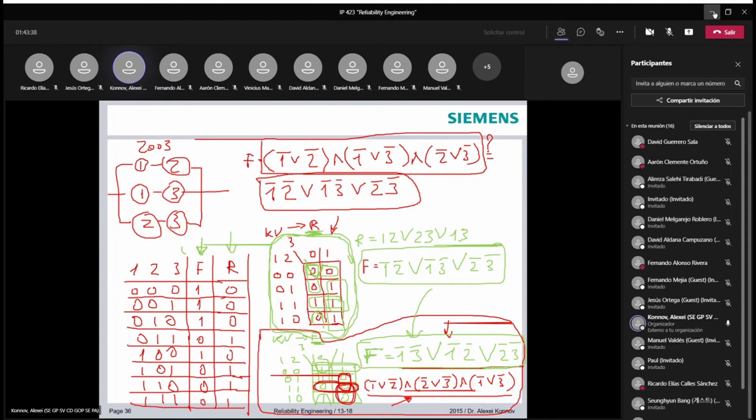But if you are not 100% sure, then just create an additional column and then you can construct the appropriate KV diagram. You will get all of the necessary results in DNF, like we had it here, or CNF, like we got it here. Most important, we now have the proof that that expression here and that expression here are absolutely the same. Don't be confused by that.